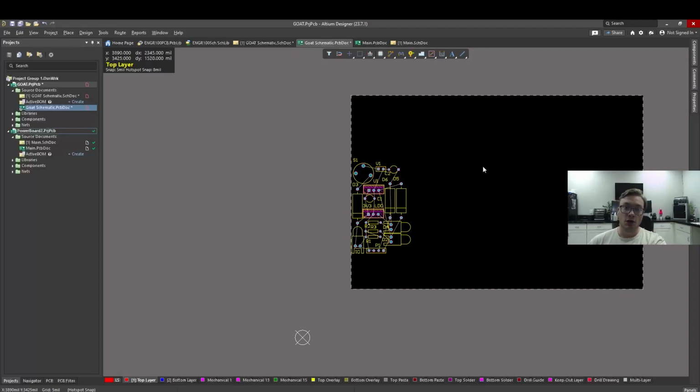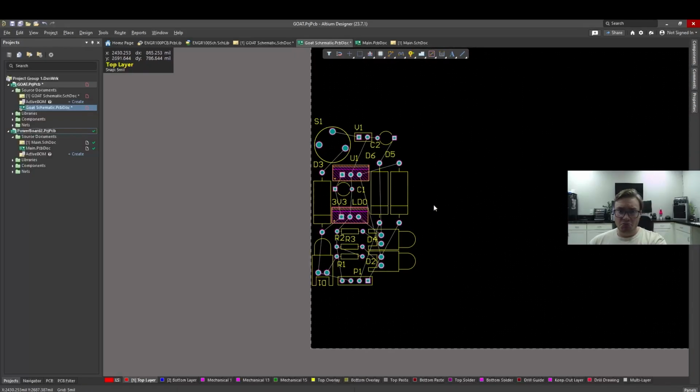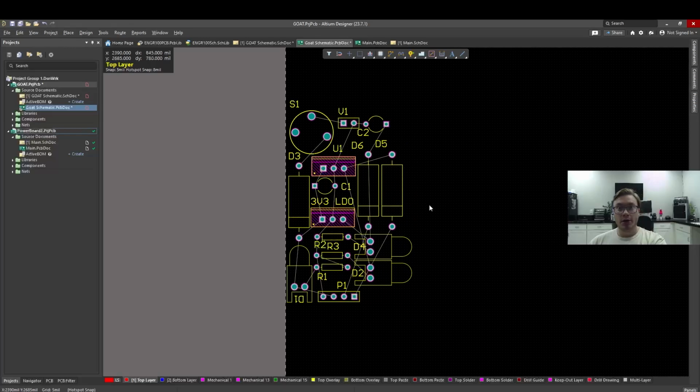All right, looks like we've got a layout. Not my best work, but it'll do the job. So, running through everything here. Battery connects here. This is our pin switch. So positive terminal goes in there when we pull the pin. This terminal connects to the protection diode.